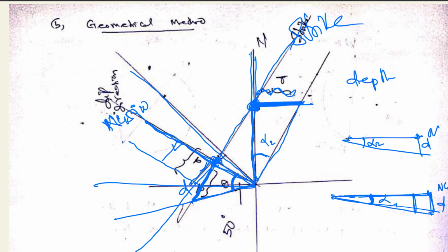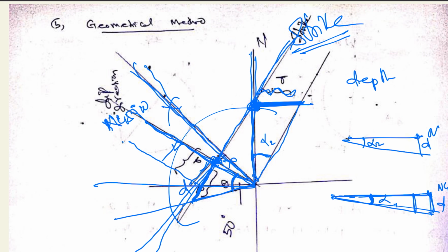These root points having d depth for the two apparent dips are joined, which will be the strike of the constant bed. Then draw perpendicular to that strike line from the center. This will be the dip direction. This will be the true dip direction. Then this is the point of intersection between the strike line and the dip direction.